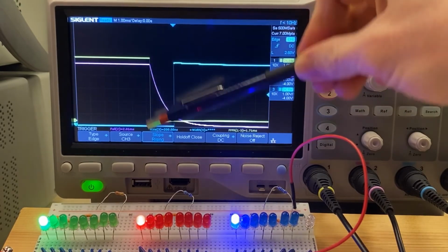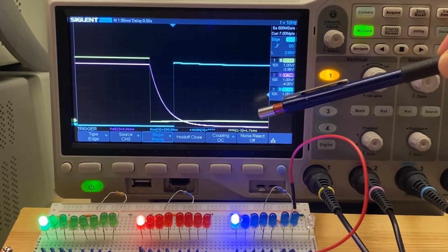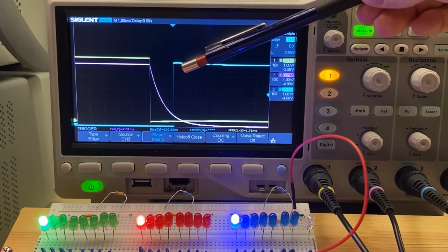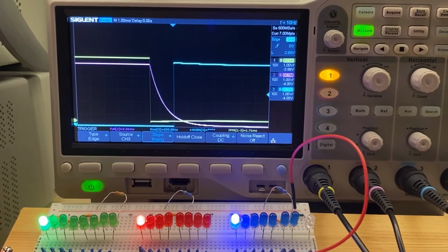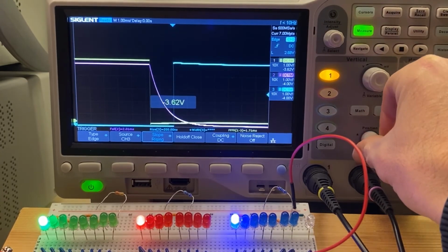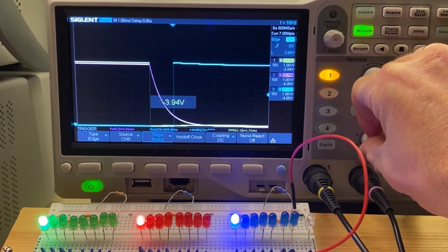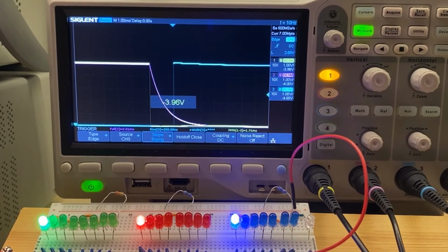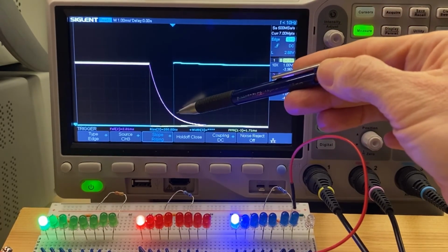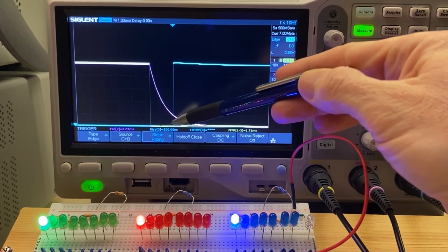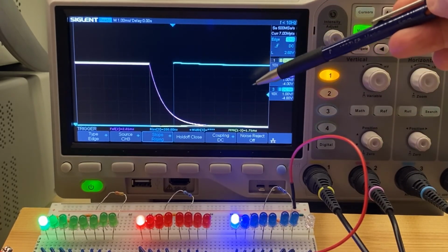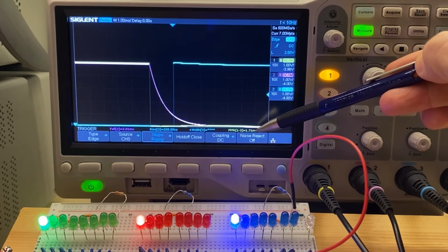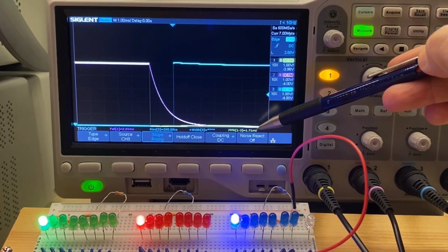So once that drops low, the node A, as we called it, on the capacitor is going to slowly discharge. Let me put them back down so you can see how it goes. And once it discharges to about a volt right here, our clock suddenly strikes high. And by that time, it says here, about 1.7 milliseconds or so.